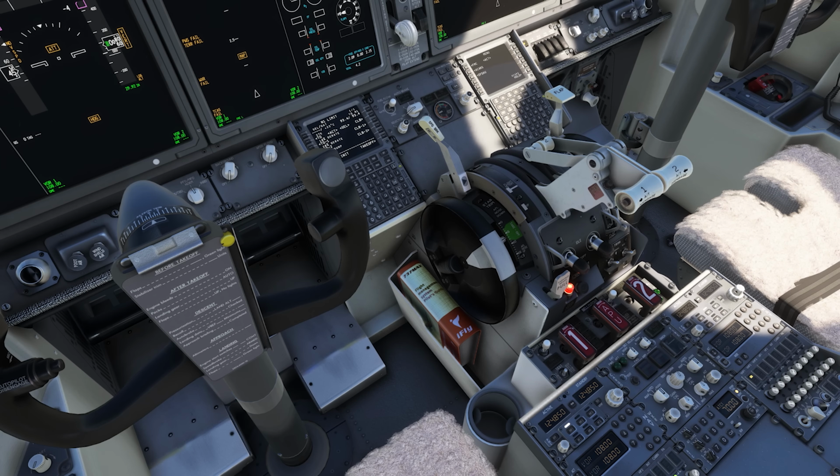So let's have a look now at the pitch wheel, because we'll talk briefly about the speed trim functions as well. Just like with the NG, there is a stability augmentation system which encourages the pilot to return to the in-trim speed by trimming in the opposite direction as the pitch force. We then typically trim those forces out when it activates, which is usually at high thrust settings and aft weights. And a part of that system is MCAS.